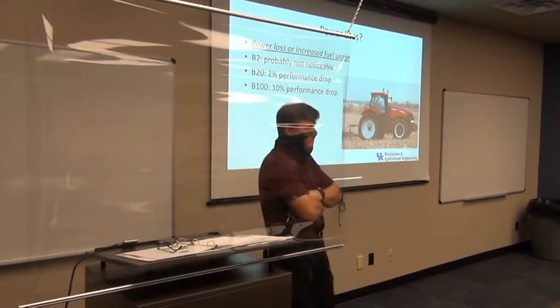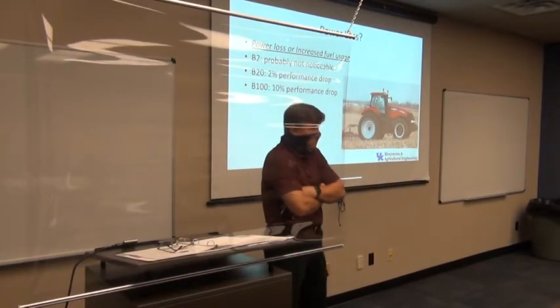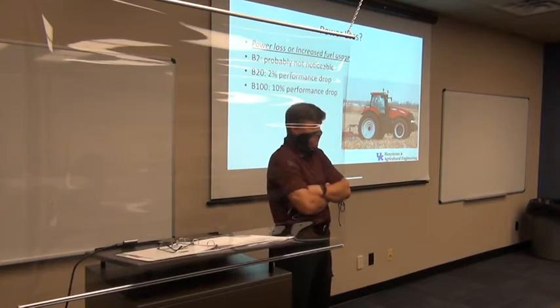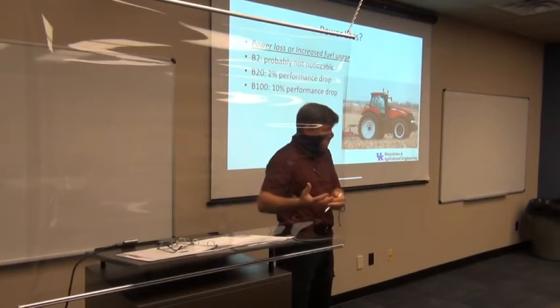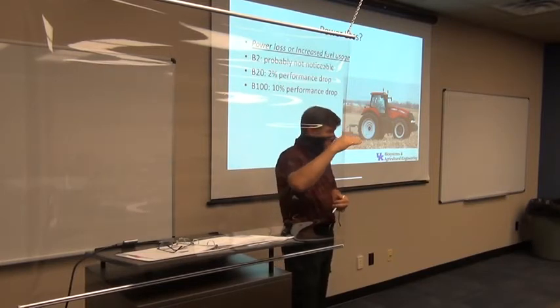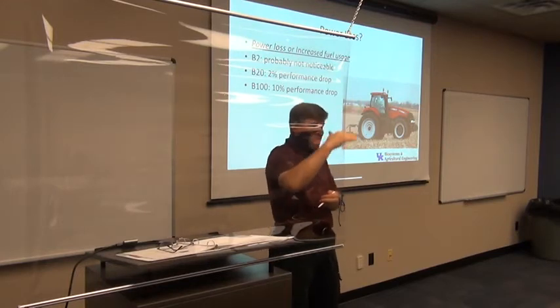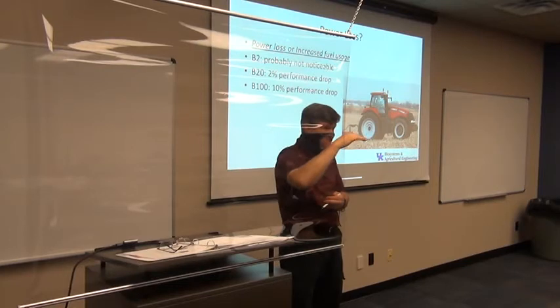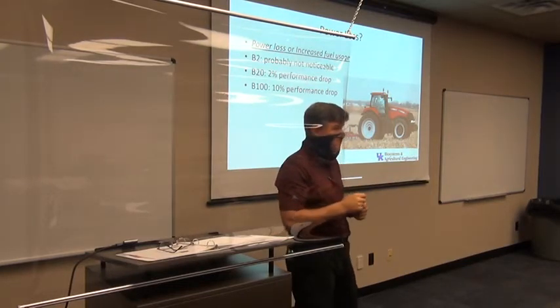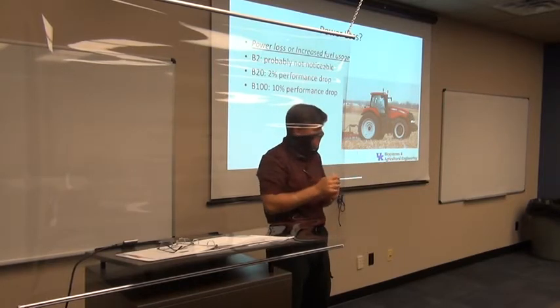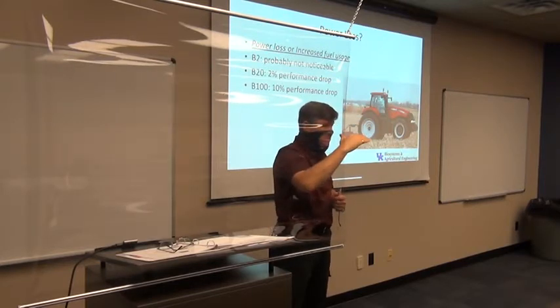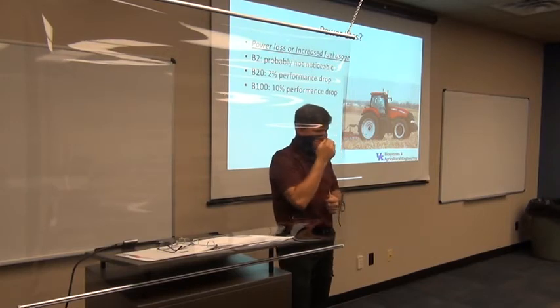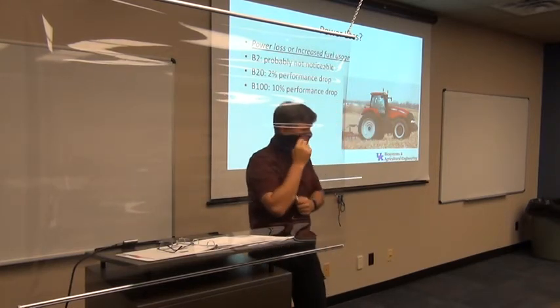No, let's think through it. So what do you think? If there's not as much energy in the fuel going through the engine, am I going to get as much power out of it? What does logic tell you? If there's not as much energy there, I'm probably not going to be able to get as much power out of it. So there's a good chance that I'm going to see a performance drop, in that the torque that I measure is going to get lower, or the power output is going to be lower. It might change the shape of the curve a little bit. It's kind of hard to tell, but that's one thing that I can probably expect. Lower energy density fuel, I won't get as much power out of it, unless something else might happen.